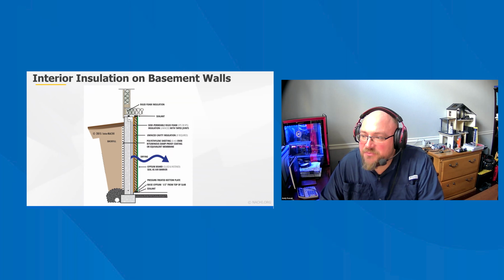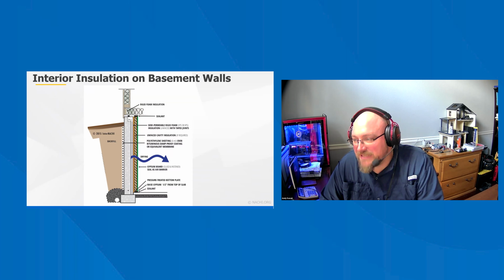The requirement of having spray foam insulation be protected by a thermal barrier is found in the 2015 IRC Section 316. In most cases where spray polyurethane foam insulation is installed, the foam should be separated from the interior living space by an approved thermal barrier of at least half-inch gypsum drywall, 23/32 inch wood structural panel, or a material tested to meet acceptable criteria by the National Fire Protection Association. There are a few exceptions to this requirement, including flame spread index ratings.